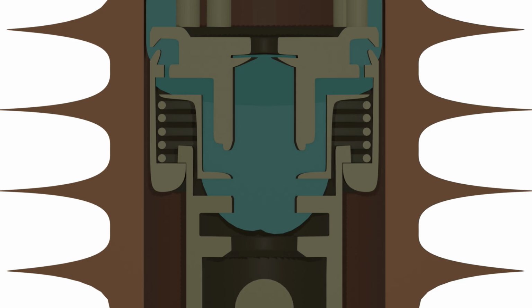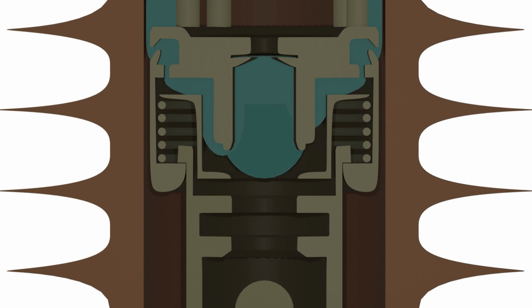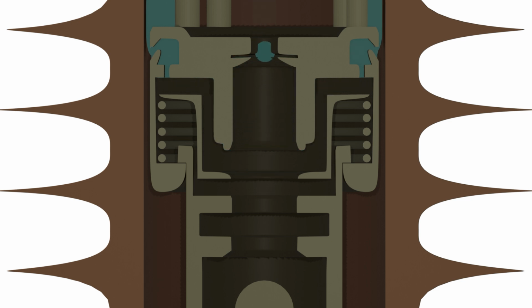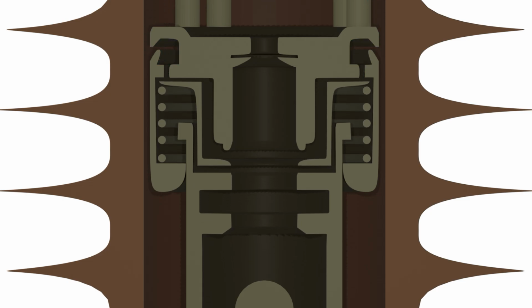Since the gas flows along the arc axis, this type of breaker is called an axial flow MOCB, minimum oil circuit breaker. After arc quenching, the gas escapes through the vents. At the current's zero crossing, the arc naturally extinguishes.